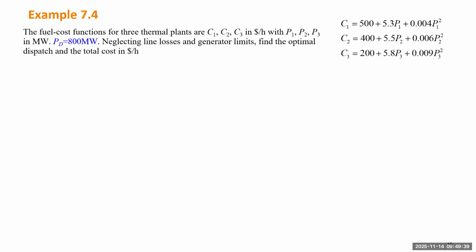Let's use one example to explain what happened by those step 1, 2, 3. We have 3 thermal power plants with cost C1, C2, C3. They're all modeled as quadratic function. So the constant value indicates the minimal cost, right? Even if you don't generate any power, you still need to pay this price for the unit to operate.